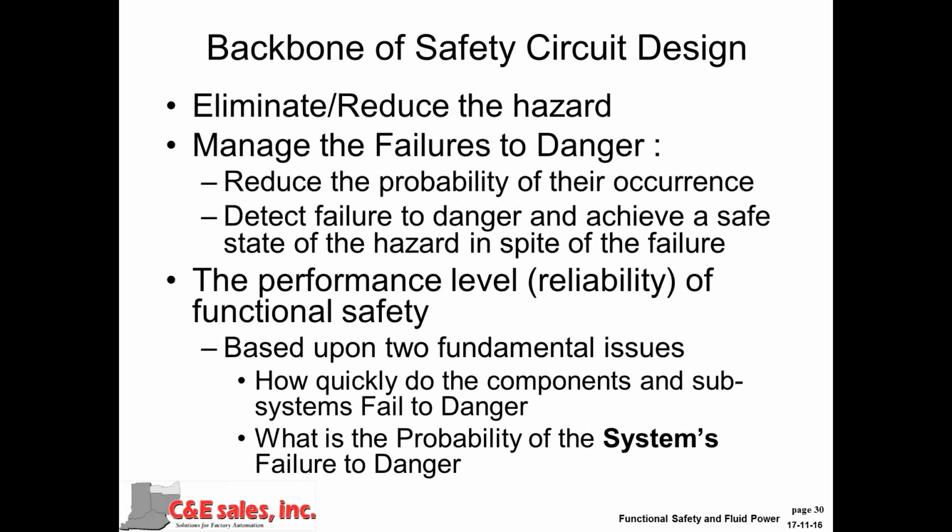For example, might be a contactor dropping out on an application where the contactor drives a motor, the failure to energize the contactor would not be considered a failure to danger. Failing to drop out would. Conversely, if you were designing sump pumps on a submarine, you may want to default to the pump running rather than not running. Failure to run would be a failure to danger in that case. So you need to understand what those failures mean.